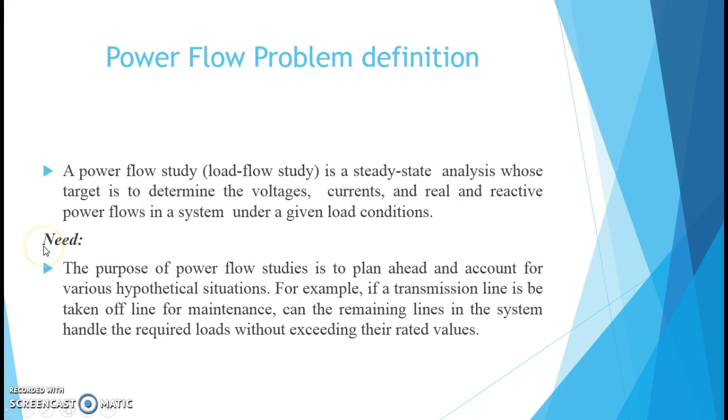Next, we will see the need of power flow analysis. Why we do power flow analysis is to test the system for different hypothetical situations. For example, if I want to take a line out for maintenance, I have to know prior to the outage whether it affects other parts of the system; otherwise it causes severe effects.